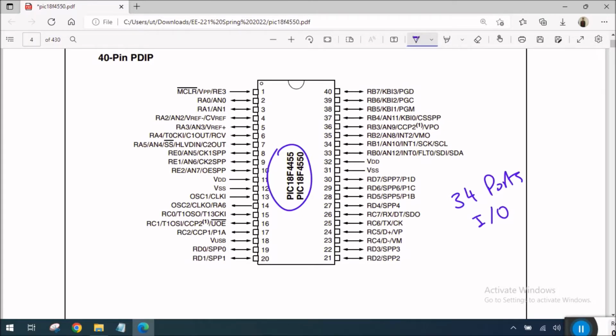For a port to work properly, we must have an option to configure it either as an input port or as an output port. A single port cannot work as an input and an output port at the same time, and I'll tell you why. When I say the term port, technically each of these pins is a port where an input or output can be taken. But conventionally, we refer to a set of pins as a port that belong to a single register inside the microcontroller. So we can use these terms interchangeably.